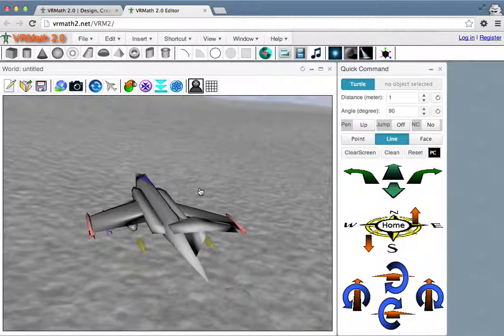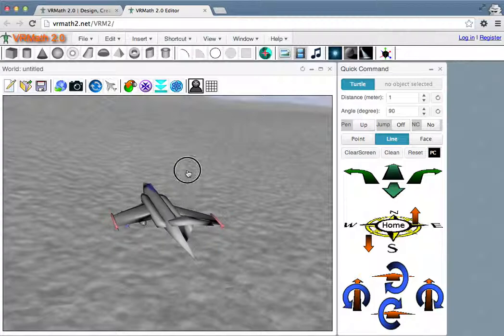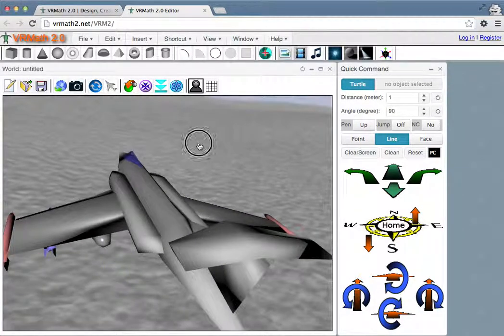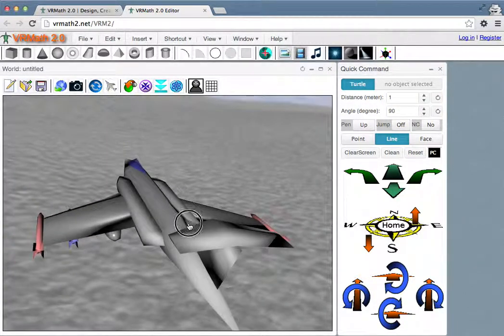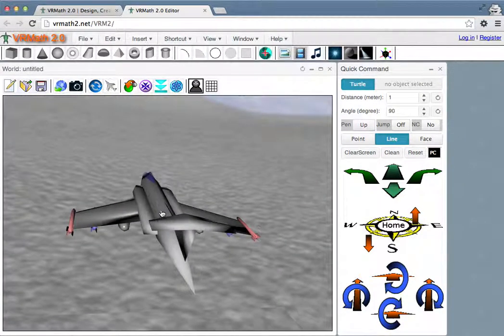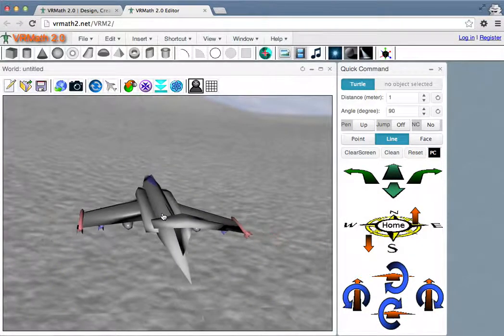Now, if you hold down the Alt key, or on a Mac computer the Option key, and then you drag forward, it's actually zooming out. If you drag backward, then it's zooming in. And if you use a Magic Mouse or on PC, you don't need to use any key. You can use the scroll on the mouse, and then you can zoom in and zoom out. All right.